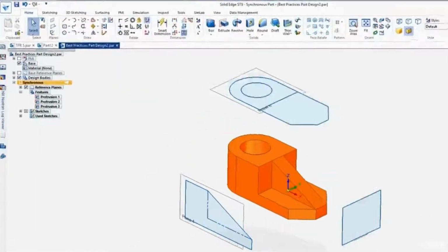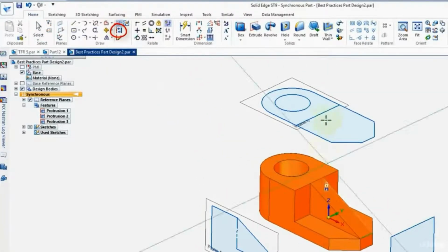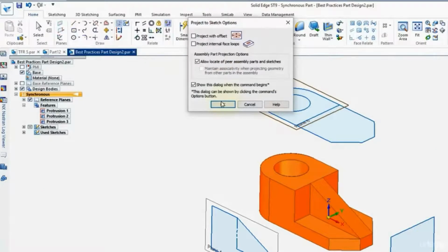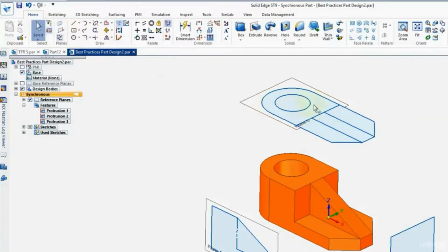Again, if I turn off the lock and go to construction and say I'll use this sketch up here, and I would like this line and this line just as reference to see where I am and to take a number of measurements. If I go here now and say I'd like to use this and project it, it's 3 different regions there. But again, if I go to construction, I can just say, look, these are just reference lines. And so now it just sees this as one region.